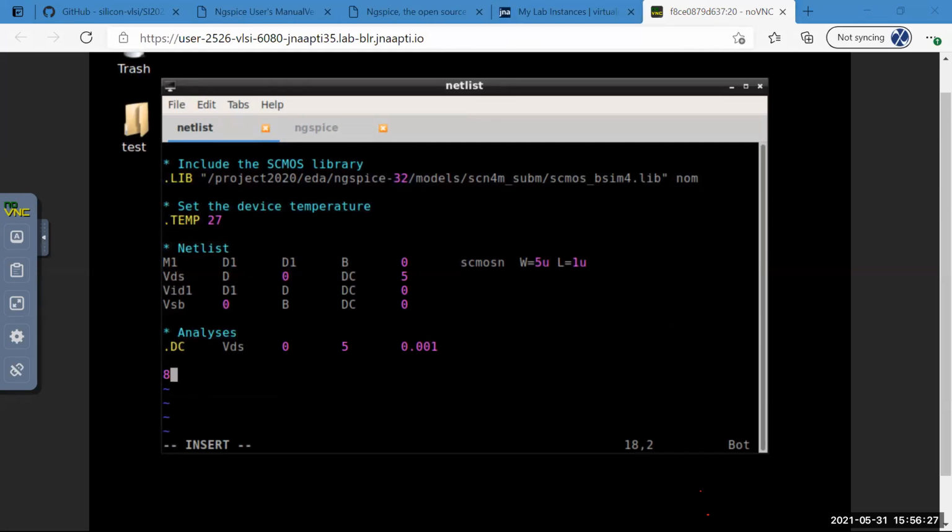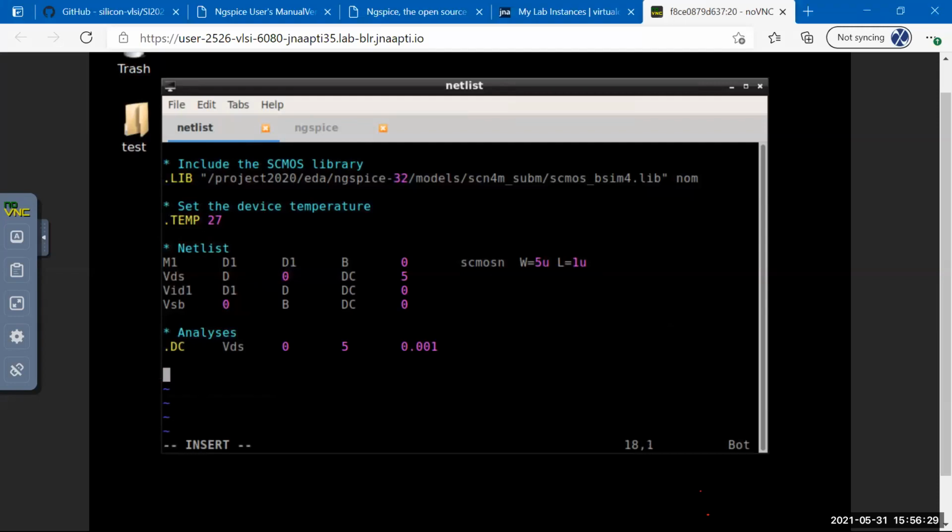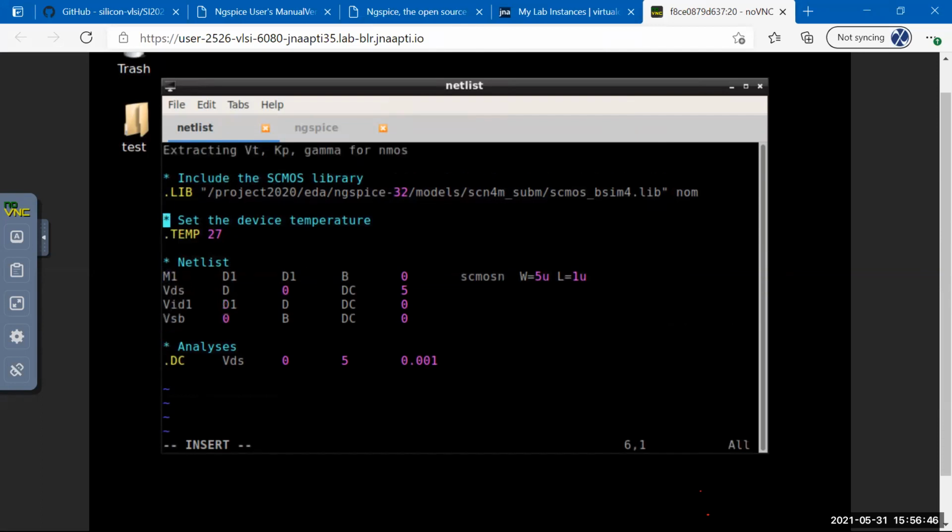Okay. So now you have to remember the dot control is actually very specific to NGSPICE. There are a lot of SPICE type simulators like Smart Spice, Hspice, Eldo and all those. They're SPICE based simulators, and most of these commands will be very similar in most SPICE simulators. But dot control is very specific to NGSPICE. So if you're using another SPICE simulator, this will not work. But we are obviously using NGSPICE, and in NGSPICE it's called the NGSPICE script.